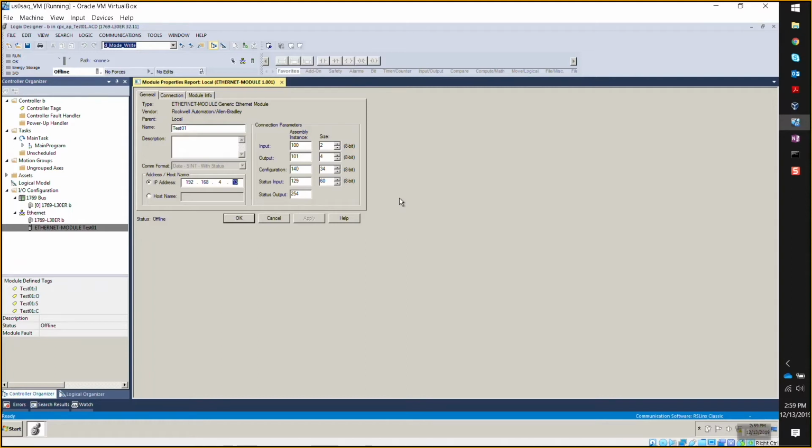Now for the exact configuration, you added that additional module, so now there's 2 bytes of input data and 4 bytes of output data. Yeah, that's what I was going to ask you. These numbers look different. So initially, the first time that we did this was with the generic module, right? And when we did it, it was 1. But since then, we added this additional module. Exactly. So now it's 2. And then on the outputs, I had 3 initially because of the manifold. And now with this new module, I have an additional byte of outputs.